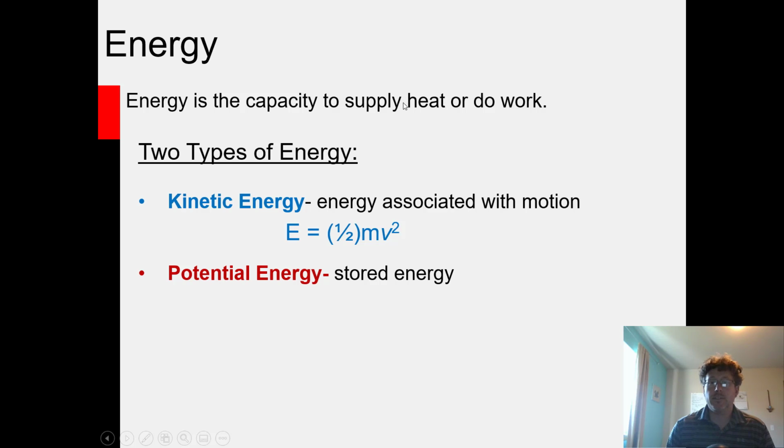The release or absorption of heat by the system, so heat into or out of the system, or what we call work. Work you can think of essentially as expansion or contraction against a constant pressure. For instance, if you're inflating a bike inner tube with a hand pump, you are doing work forcing air into the inner tube and causing it to inflate against atmospheric pressure.